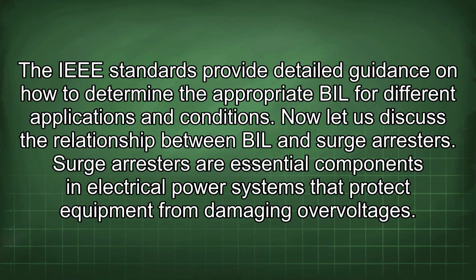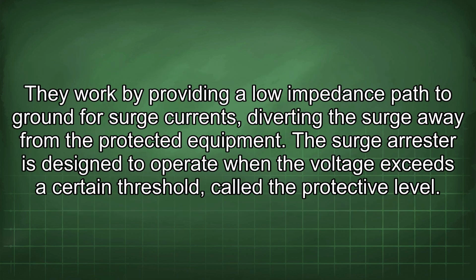Now let us discuss the relationship between BIL and surge arresters. Surge arresters are essential components in electrical power systems that protect equipment from damage in overvoltages. They work by providing a low-impedance path to ground for surge currents, diverting the surge away from the protected equipment.